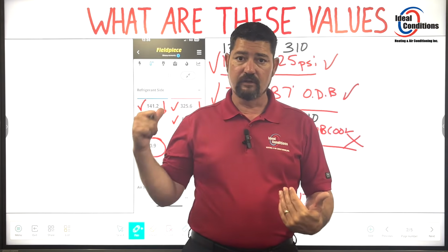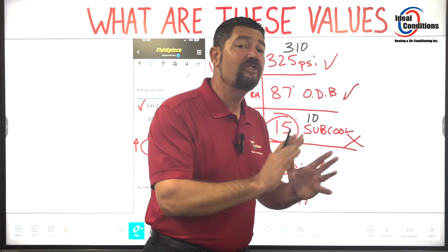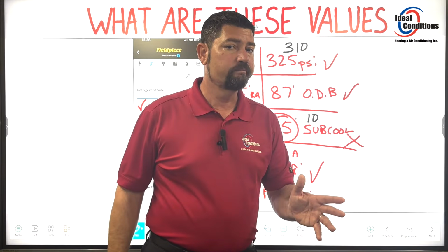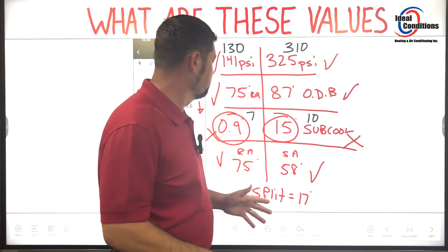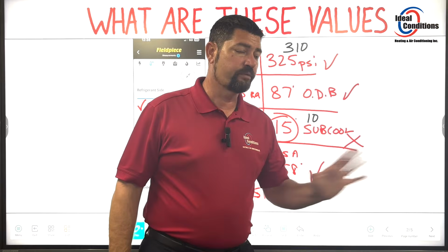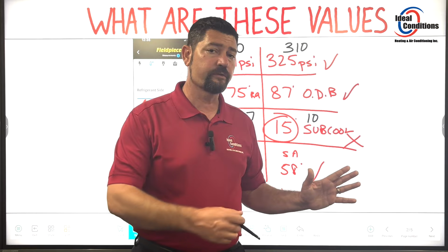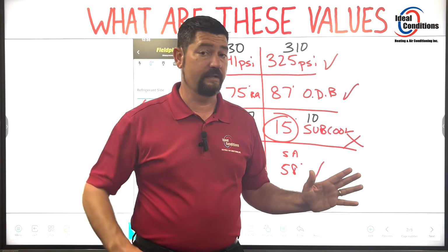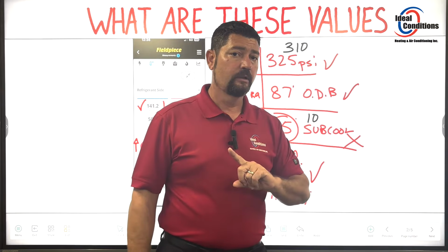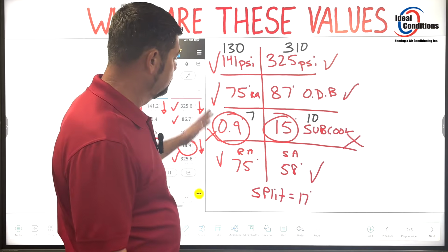If you're at this point, you should already have made sure you had a clean coil. But there's a possibility I could have that in addition to the guy that came out maybe 6 months ago, who saw everything not right, and he added Freon to it. So maybe the first problem never got taken care of. That's the neglect part. And then it was further neglected by the guy working on it, and he just added more Freon. That would be 2 different problems. But let's just say I just had one problem for simplicity.